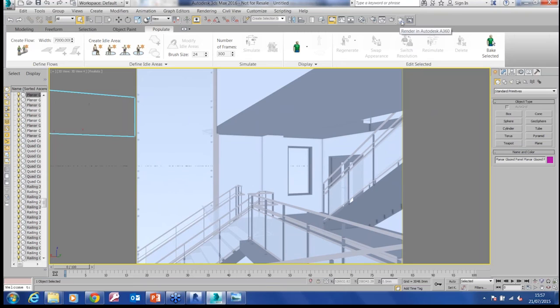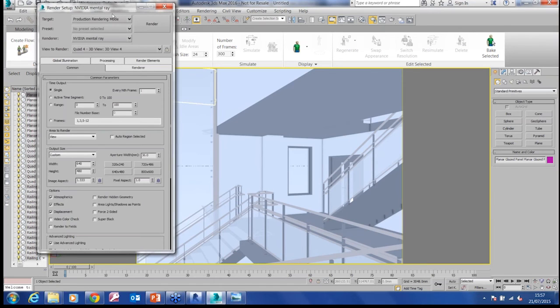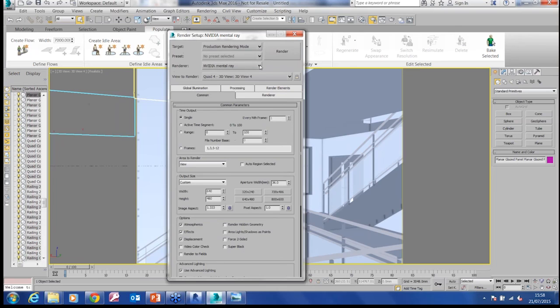Do be aware though there is also a maximum resolution as well. Okay, so if you wanted a very, very high resolution image, then you're going to struggle if you're using the cloud to actually render. Okay, it is going to give you some limitations. But what we also have is there's other renderers built into the way that we work. So at the moment, I've been using Mental Ray and showing you that today. So we actually have in here as well something called iRay. So iRay is an iterative renderer. So it renders slightly differently. It gives a slightly different effect, yeah.